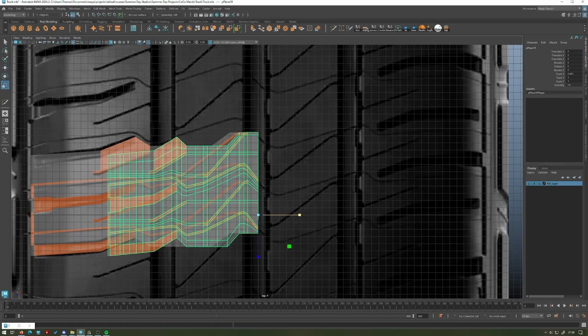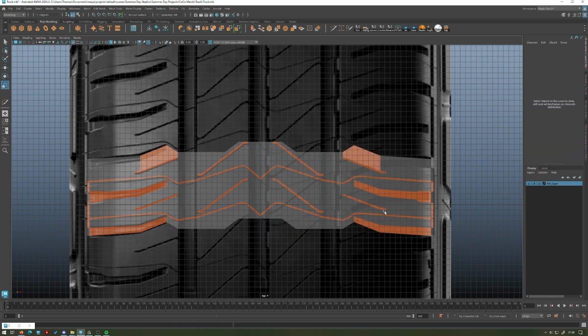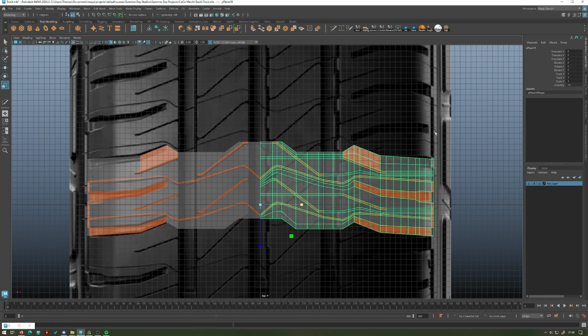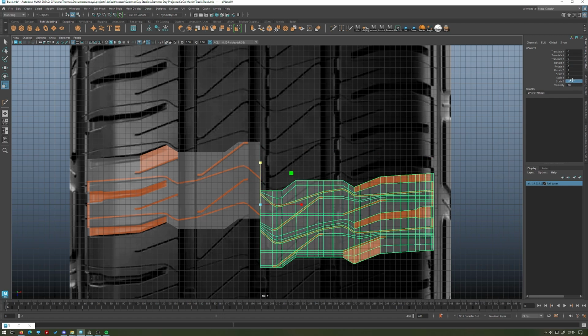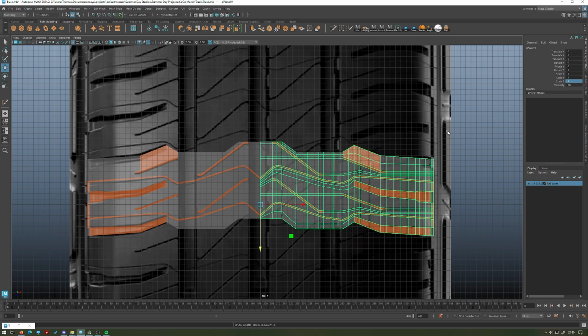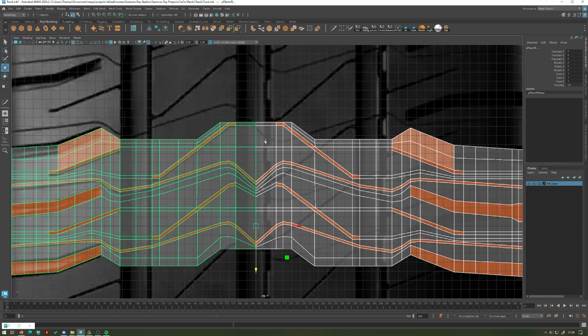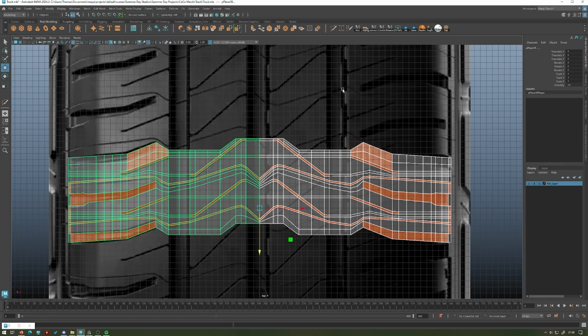Okay, so let's go ahead and duplicate that across, and -1 in X. So that's not quite matching up to the pattern on the other side. I think for the scope of this video, we're not going to get into creating some extra crazy super duper pattern, otherwise this video is going to go on forever. If you want to make it so that this side matches up, you would have to do a -1 in Z as well, and then get this to line up. You can now see we have a gap here. So there's a fair bit of work you're going to have to do to get this pattern to adjust and still be tileable without gaps like this. For this tutorial, we're going to go ahead and leave it like this. Every single tile is different. This perfectly matches up. I'm happy to leave it like that for this.